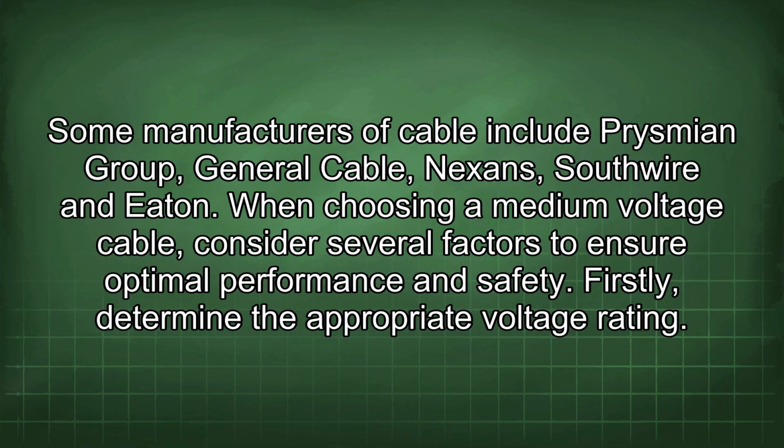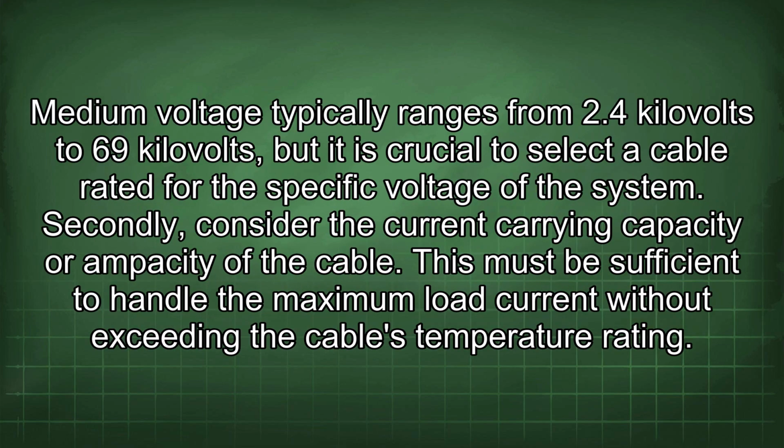When choosing a medium voltage cable, consider several factors to ensure optimal performance and safety. Firstly, determine the appropriate voltage rating. Medium voltage typically ranges from 2.4 kV to 69 kV, but it is crucial to select a cable rated for the specific voltage of the system.